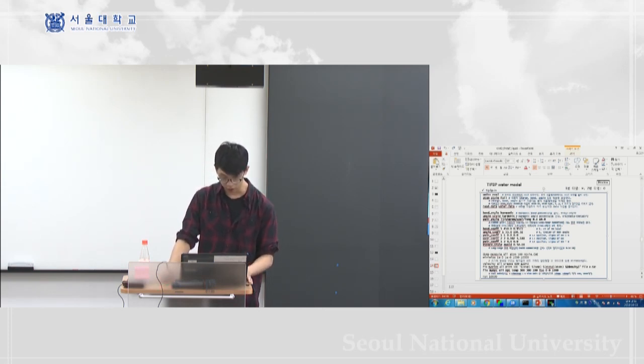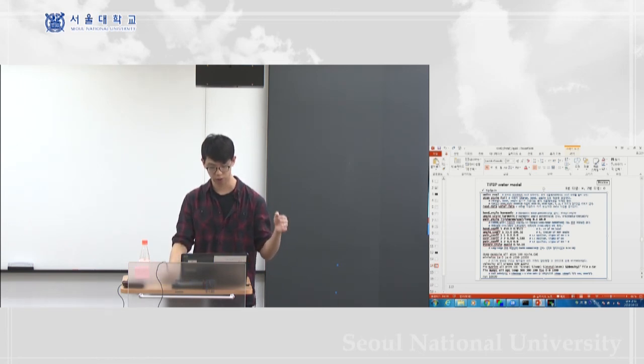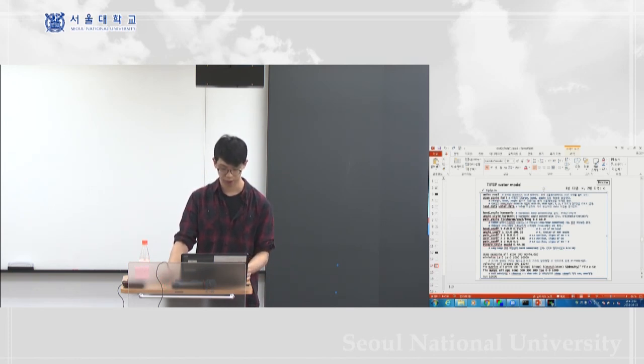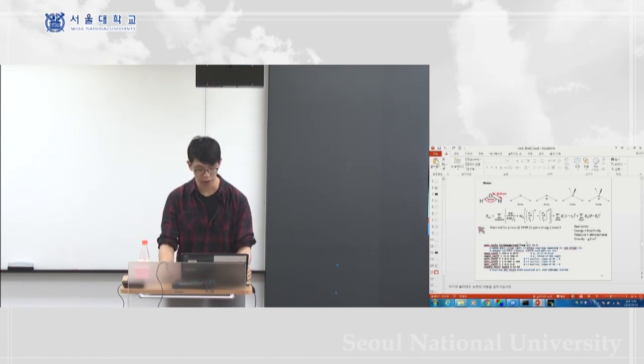And the angle style is also harmonic. And the pair style is the potential for the intermolecular interaction. The bond style and the angle style are the intramolecular potential, and the pair style is going to be the intermolecular potential. It's going to be the LJ charmm Coulomb long potential style. And all these are the parameters for the potential. So here, basically, we're going to use this type of potential, which is TIP3P, and all the parameters are set up here in this command.